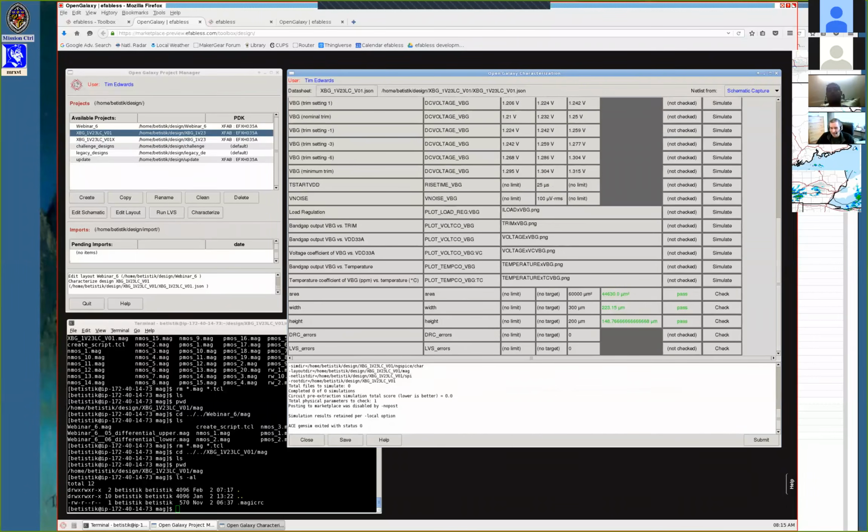That valid netlist has to be in place before it can do all these estimates, for instance. So if you run this and it fails, you can just run one of these simulations. That will give you the correct netlist output, and then you can run these. Likewise, the netlist is what it uses to create the initial layout.